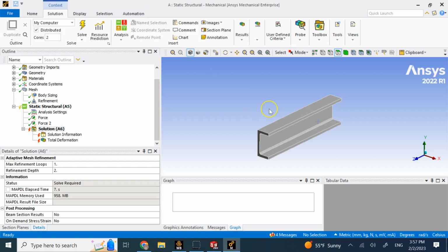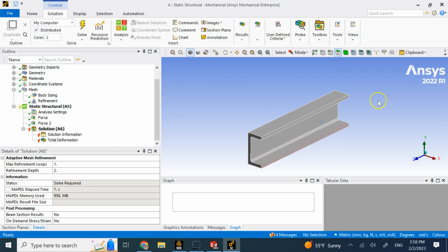So if you do not constrain the degrees of freedom, and just say that because of the balance of the forces the object is in equilibrium, guess what? It is going to pick on you, and it is not going to give you any result, as you can see here with these reds. There is definitely a problem, and the object is physically moving, so it cannot calculate for you what you want.